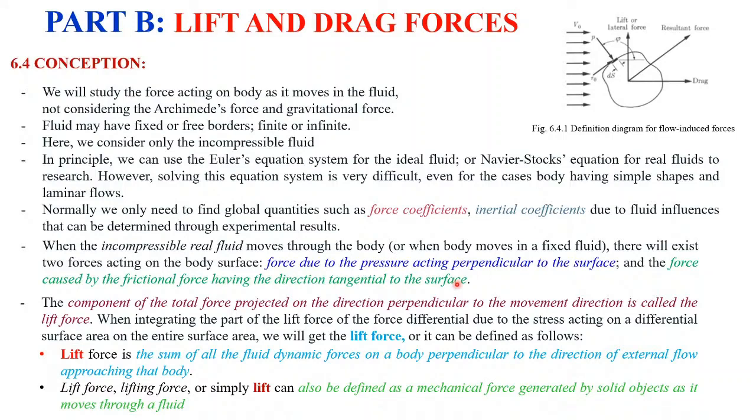The first component is normal to dA, due to the pressure, which we call the pressure force. The second component lies in dA, tangent to dA, caused by friction, which we call the friction force.